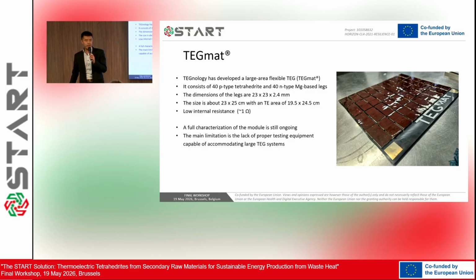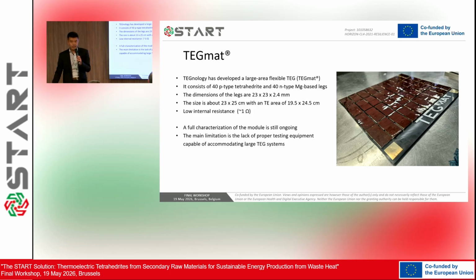We actually need this big footprint because, as mentioned, when we cover huge areas, in order to build up the voltage, the current is going to be very high, even though the delta T is small. So we need the legs to run bigger currents. And that's why they end up in this way.